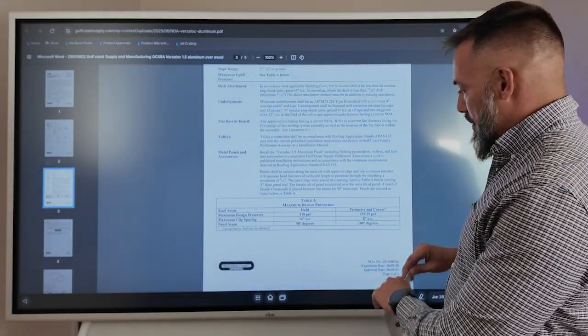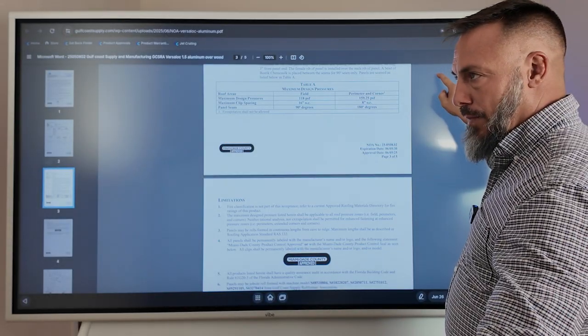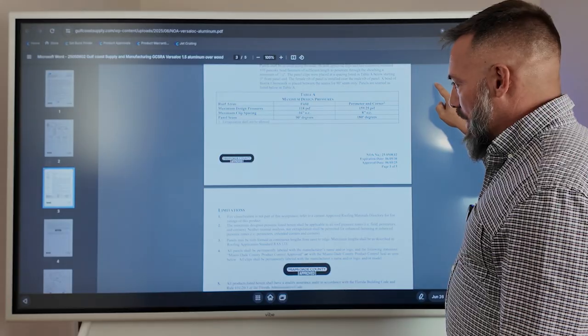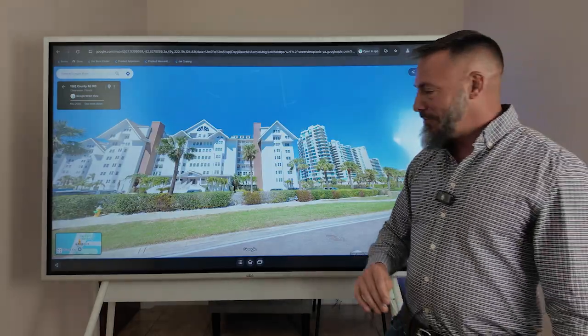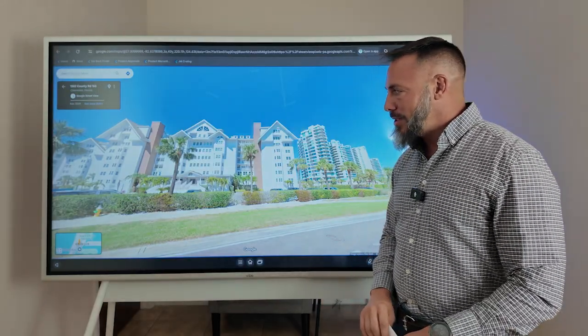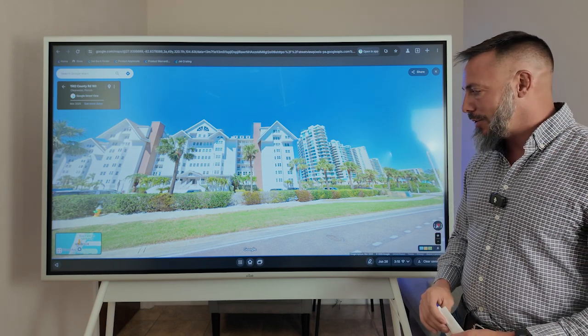But this does not give you a conversion chart. So I can still use the conversion charts from the other Florida product approval to figure out what my pressures need to be per structure. So that is how to convert wind speed to pressure to determine which panels you can use on your roof and to determine your fastening pattern for that roof.